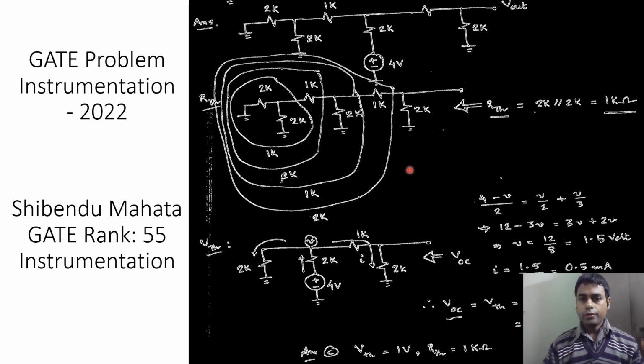So here is how to approach this question. Let's first solve for the Thevenin resistance RTH. With switch A we connect it to ground, with switch C we also connect it to ground, and with switch B we directly connect it to this 4-volt source. Our objective is to find the resistance looking from this output node. The first thing to do is to deactivate this 4-volt source. Because this is a voltage source, we replace it with 0 volts, and basically this ends up getting terminated to ground, and there are no dependent sources.